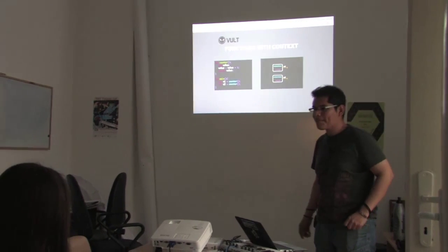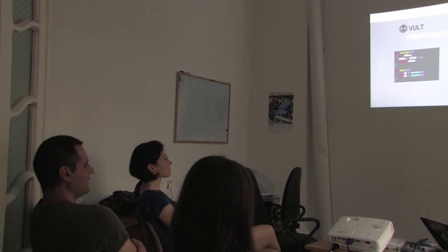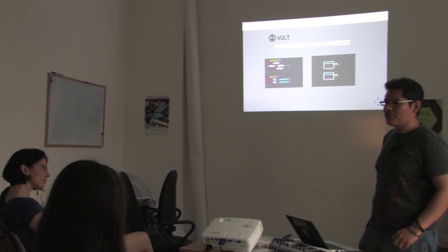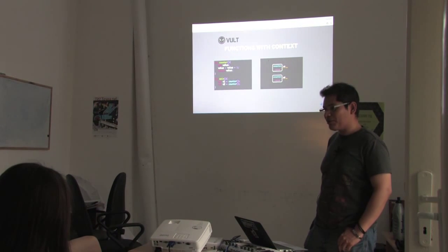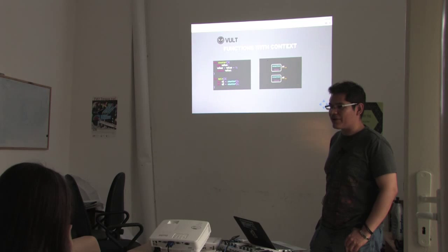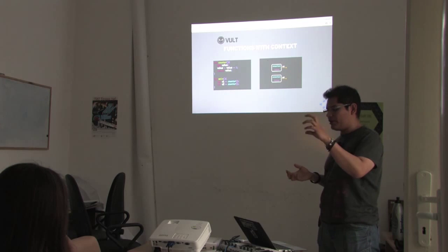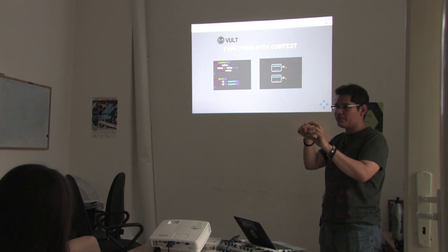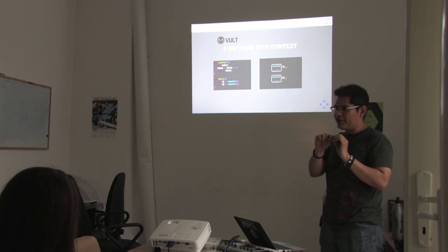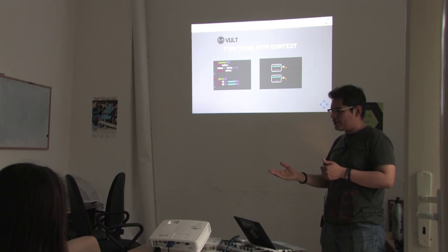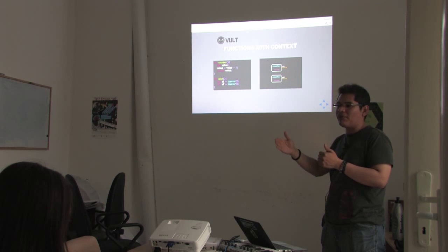So if you want to do something in the frequency domain, something that requires buffering, you can't. No, not yet. It's going to be possible when I implement the arrays and tables. But currently it's single point. There is one nice trick: if you want to do frequency domain, you can put a frequency transformation at the beginning, and then you have the FFT, and the information that you pass are the actual samples of frequencies.